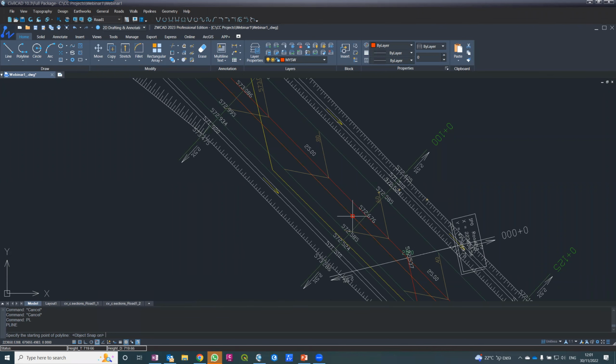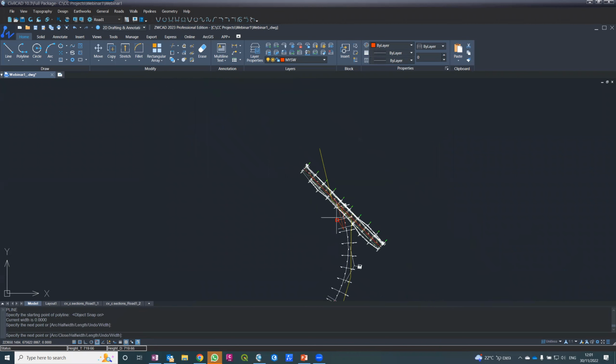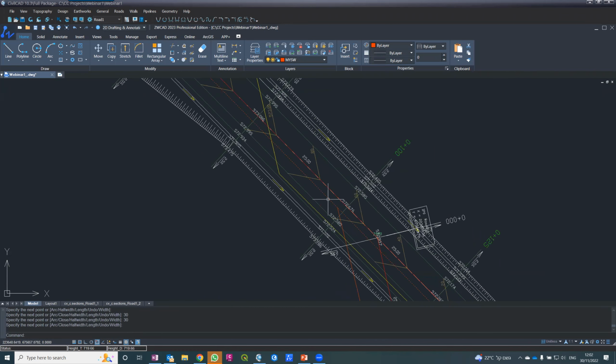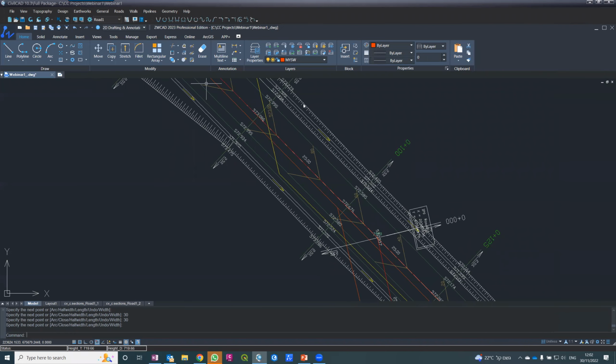And from this vertex, let's say it goes like this. Another pipeline, 30 meters, 30 meters. So I have two pipelines, this one and this one. But now I just have a polyline, so I want to convert it into a pipeline. So I'm going to pipeline list. This will be the first one, and the second one will be 2, and both of them are sewage, with a round profile, and using millimeter as units.